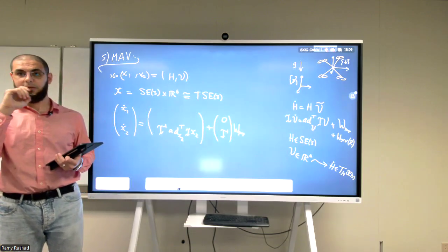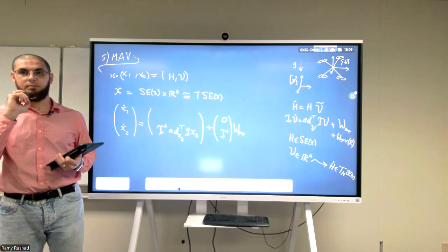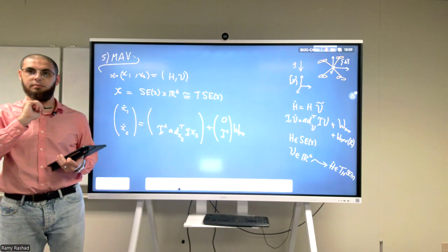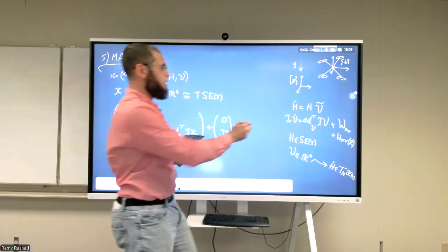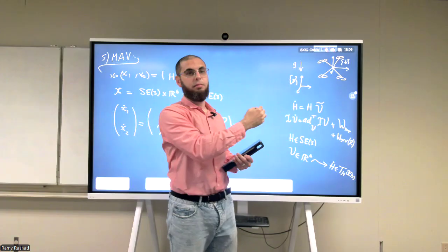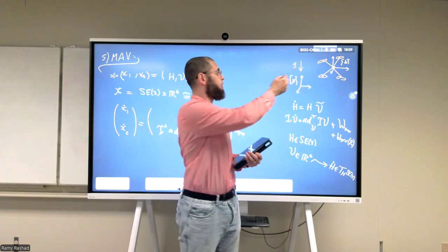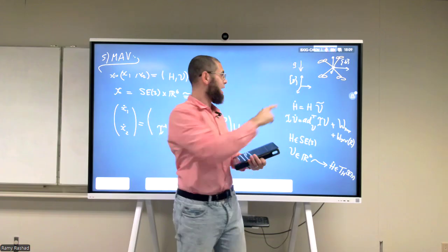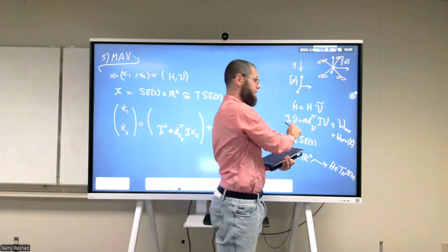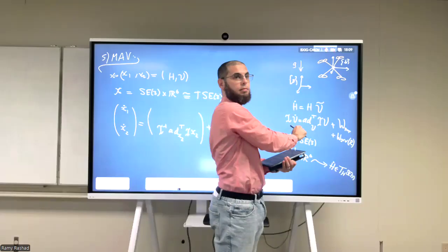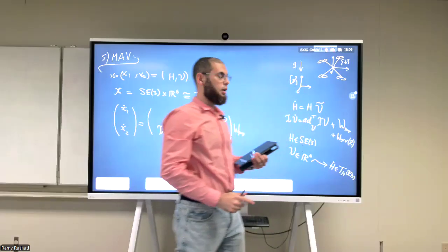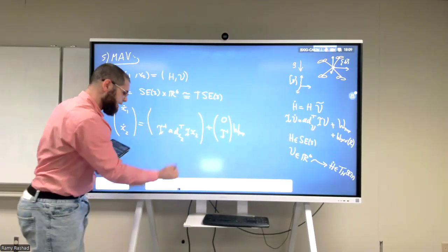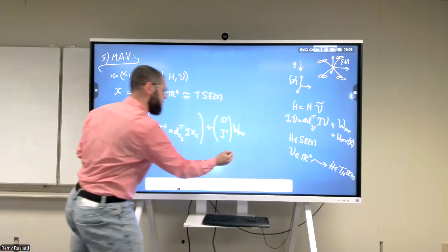If the drone was in some orientation, the gravity would be different. That makes sense. Because this V is in which frame? In the body frame. And the gravity in the body frame looks different. You're thinking about gravity in the zero frame, but this is an equation in the B frame. So it makes sense now? Okay. So the gravity actually is the missing part here.